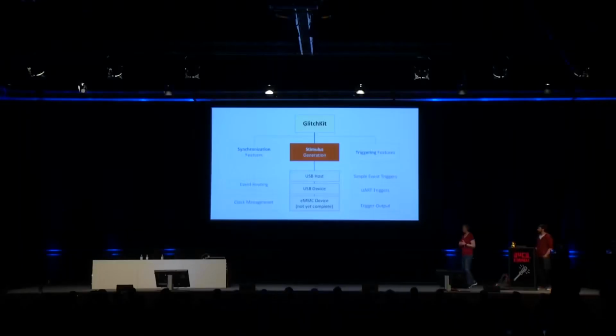So if you think that a vulnerable piece of code or a vulnerable hardware function is only ever exercised once you've received a certain command, let's say, I'm a USB device, I have the capability to self-describe, I'm only going to do that when you ask for a descriptor, you need to be able to go and start poking that device and prodding it in order to get it into a state where it's doing the tests that you think are vulnerable. And while you're doing that, you often want to know what stimulus are being applied and where they are in time, because sometimes the stimulus for triggering is I've just asked it to respond to a given command.